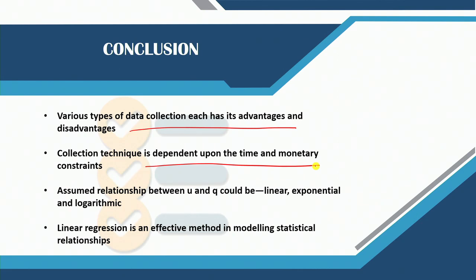Then we gave you the basic relationship between speed, flow and density, which are essential to understanding the flow characteristics of pedestrians walking along any facility. For all of those we used an example of the Greenshields model, which is a linear model, and how the linear model can be estimated. We showed you an example of the regression technique that allows you to estimate the linear relationship between two parameters. Thank you very much.